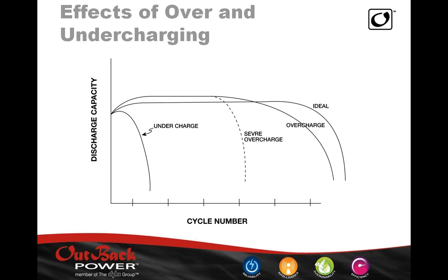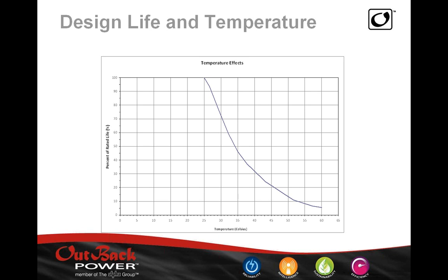So the system, at the end of the day, has to be able to recharge those batteries, and we'll talk more about that in part 2 of our webinar. This chart is essentially showing how temperature will affect the life of the batteries. The very famous electrochemistry equation basically says that the corrosion doubles every time the temperature increases by 10 degrees. So if a battery was going to give you a specific life at 25 C, at 35 C, that life is going to get cut in half.